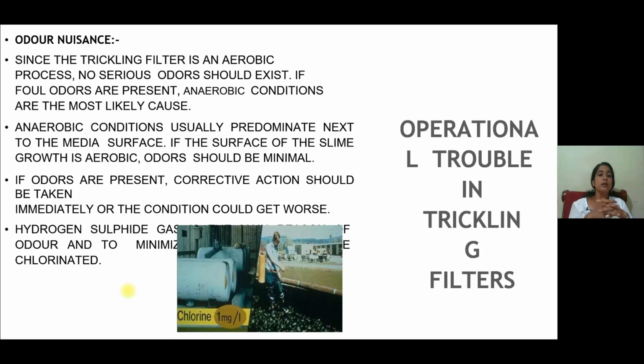And if the anaerobic conditions usually predominate next to the media surface, then this odor nuisance will happen. And if the slime layer growth is aerobic and decomposition is aerobic, then the odors will be minimum. If odors are present, corrective action should be taken immediately or the condition could get worse.